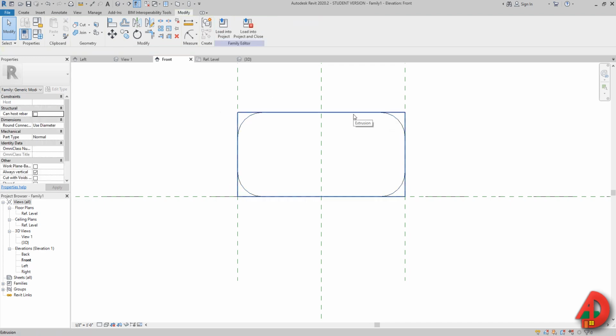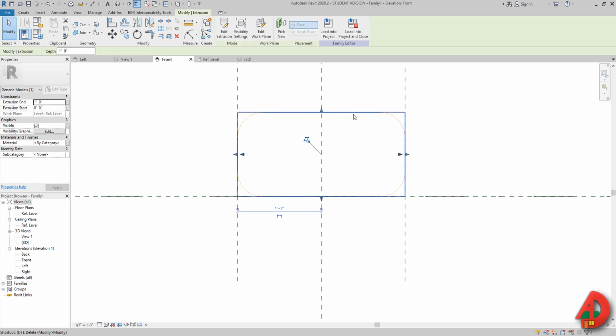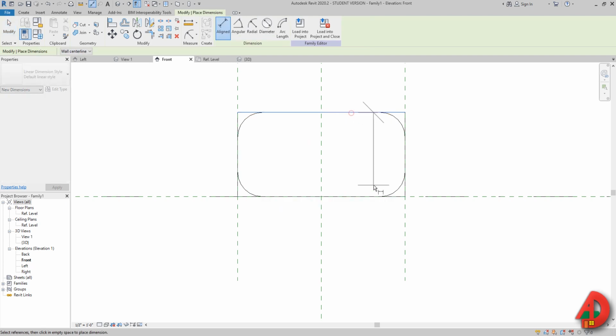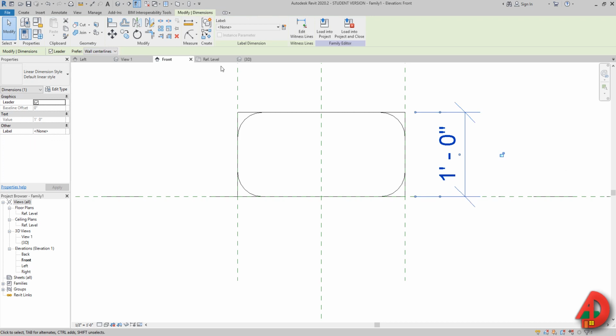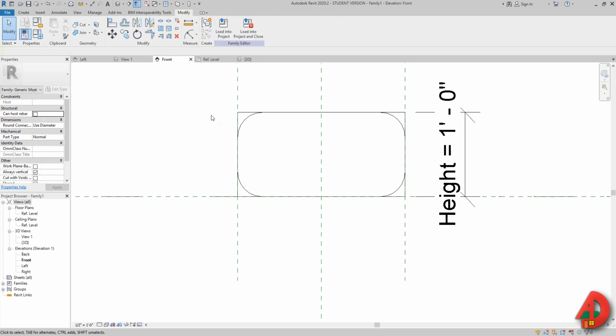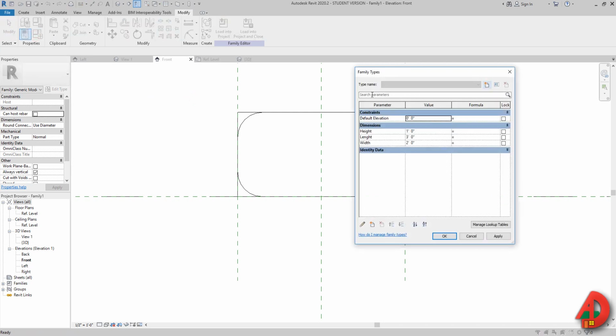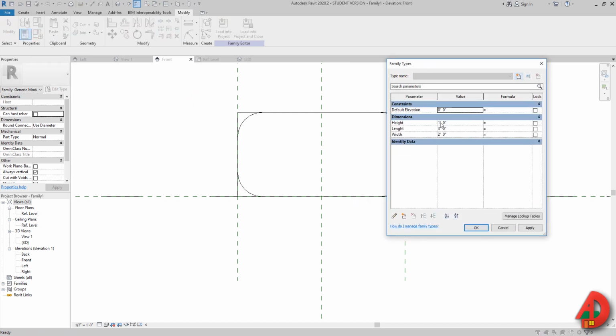And we also need to change the cube as well, the main model. That was the extrusion that we just modified, so that's going to be labeled height. Okay, so if somebody is going to use this family, here are the family types, he's going to be able to modify height, length and width as they wish.